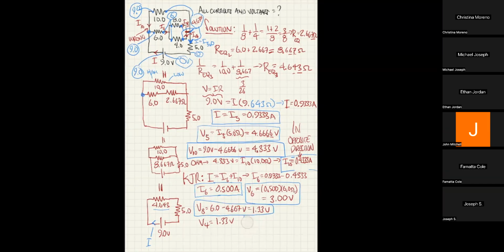Okay, so now what we figured out is the voltage of the 8 ohm and the 4 ohm part, and we do have a check, by the way. V equals IR means that we should be able to find I8 and I4. Since 8 is twice of 4, we really expect the current through the 4 ohm resistor to be twice as big as the current through the 8 ohm resistor. We only had half an amp going in, so 2/3 of that should be the current in the 4 ohm resistor.